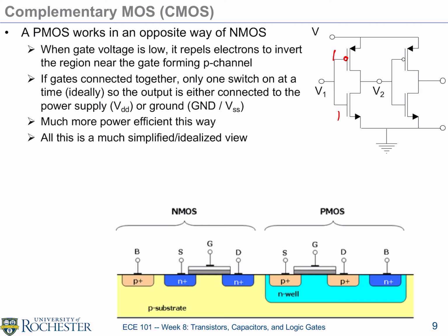In a PMOS device, when the gate has high voltage, because the body, which we've not drawn, is in fact connected to the power supply, the voltage across the channel is actually 0, and that's when the device is off. Never mind the details, which you will encounter in different classes. Suffice it to assume this model: high voltage on for NMOS, low voltage on for PMOS.